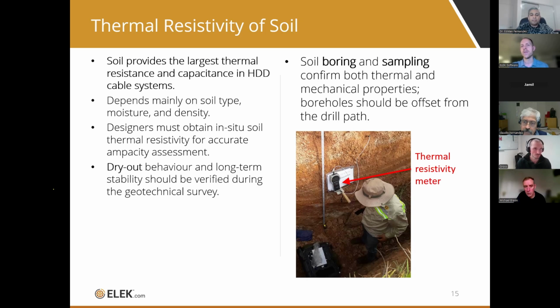So this photograph is not really what you would expect for a soil thermal resistivity survey for a HDD. It would actually involve boring and sampling. It wouldn't be a guy climbing into a hole. This is typically for another sort of standard buried installation application where you're taking samples like this.